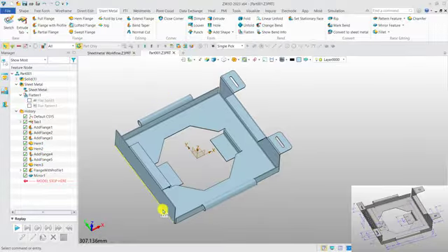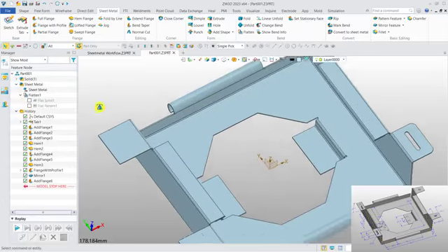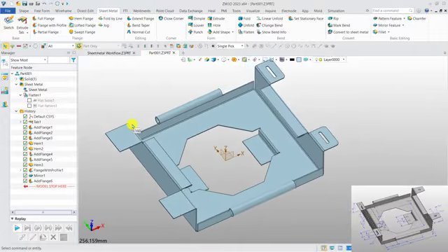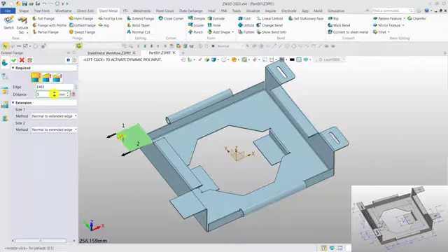And let's continue. Can make the full flange for the other side. And for the length, okay, 35. Okay. And for these two flanges, we can use the bend taper command. First, we can extend a little bit. Extend by distance 5 mm.